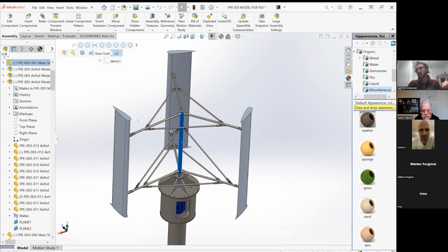In particular, we look at the worst case scenario, which is if this was static and not rotating, but you did have a wind force in one direction, what would be that bending stress on this shaft? And because it's continuously rotating, you have a continuous change in bending stress, because it's rotating while it's bent. So we look at that.